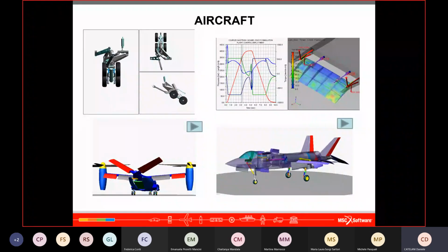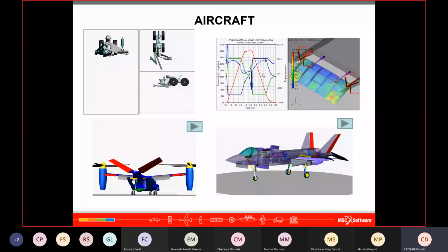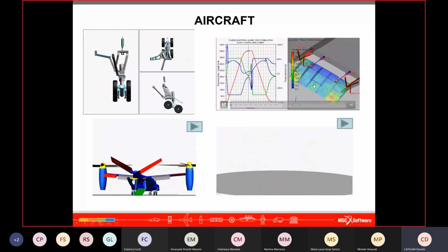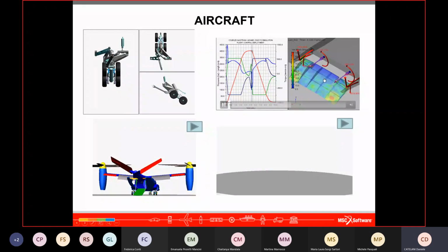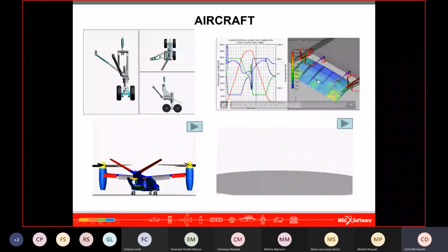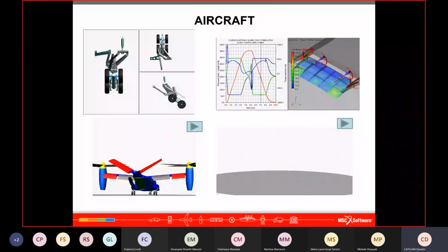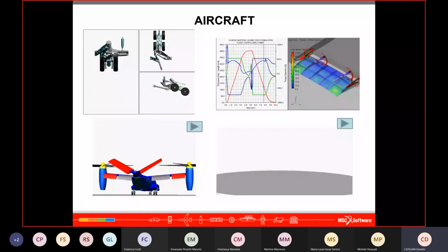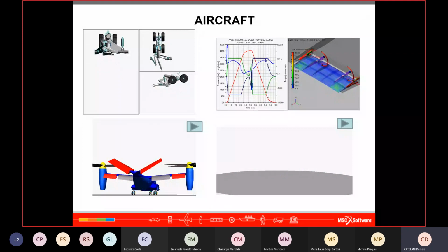So it is a mobile surface. The pilot moves and changes the configuration in order to increase the surface invested by wind and the angle of attack of the flap. Because during the landing and the takeoff, the speed of the aircraft is low, and you have to compensate this velocity with the surface and angle of attack to have the same force. Otherwise, the aircraft cannot fly.